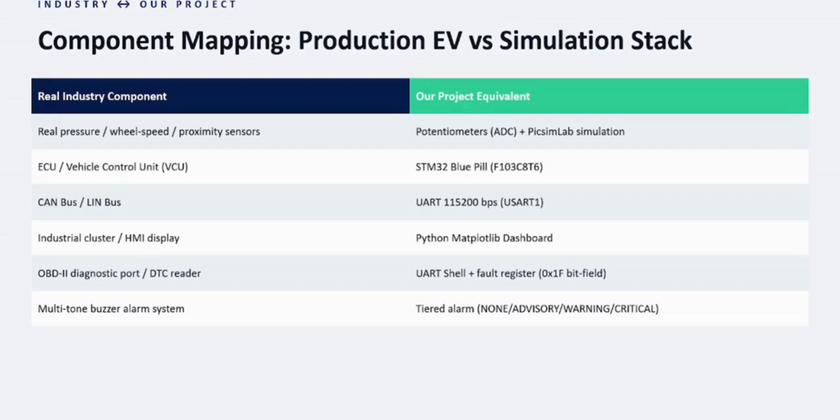The fifth phase implemented the ADAS system using the HC-SR04 ultrasonic sensor. This module provides forward collision warning, blind spot detection, parking assist, and time to collision calculations. The sixth phase added the fault detection and alarm systems. It continuously checked for abnormal situations like overheating, criticality, low battery, collision, sensor failure, and communication failure.